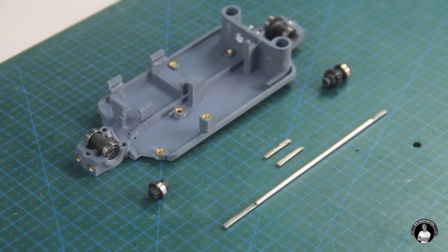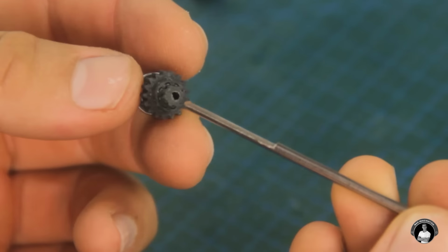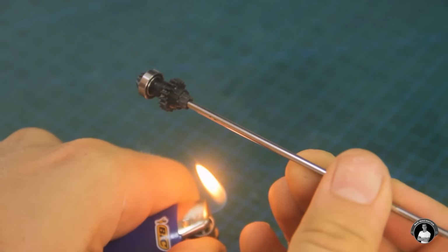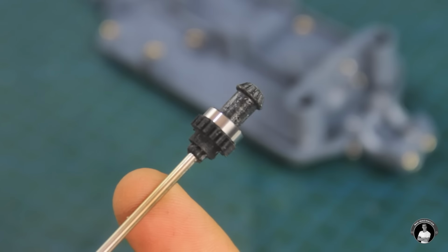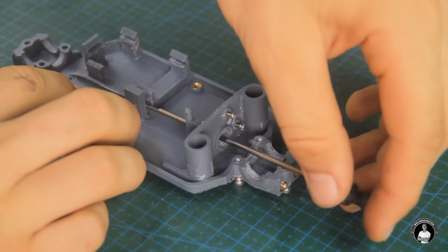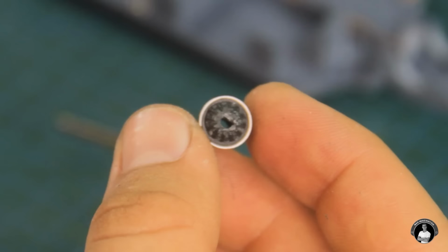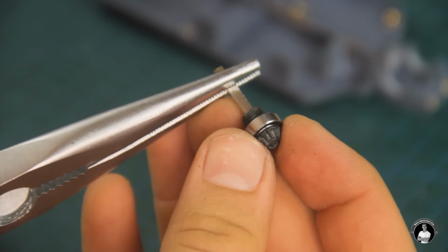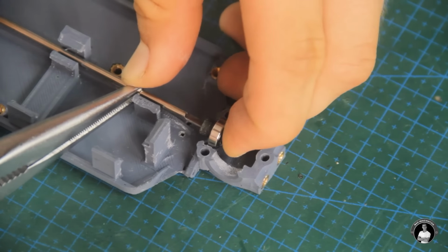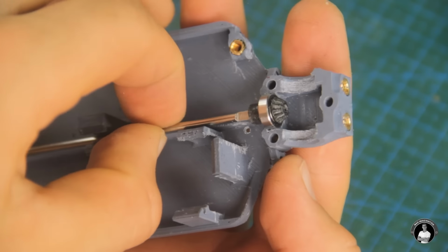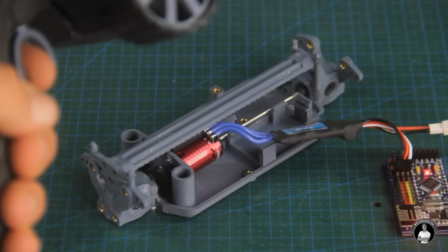Now let's work on installing these axles and the drive shaft into the gears through heating up the rod ends and carefully pushing in the rods without splitting them. However, with the front pinion gear, you may need to first wear in the connection with another axle and then slide it on with a more loose fit to the drive shaft once it is in place. Again, we'll wear in the gears for smoother rotation, now having the front ones installed.